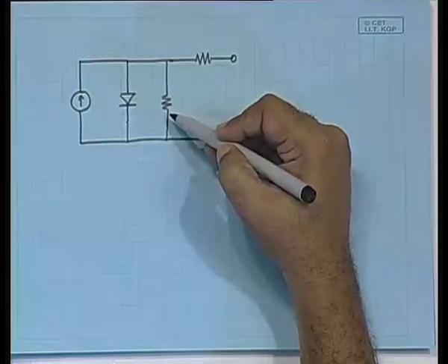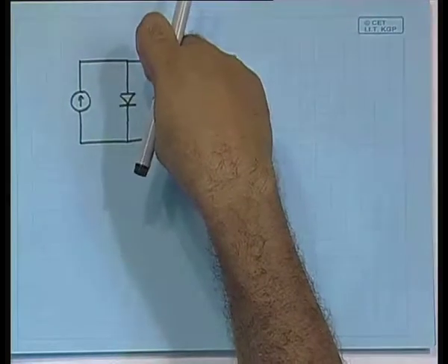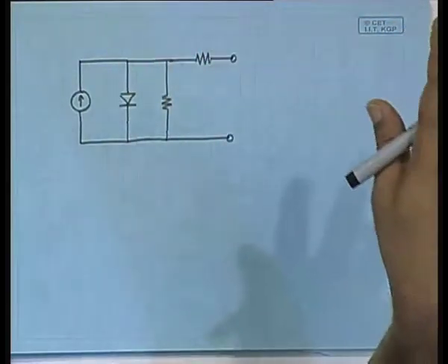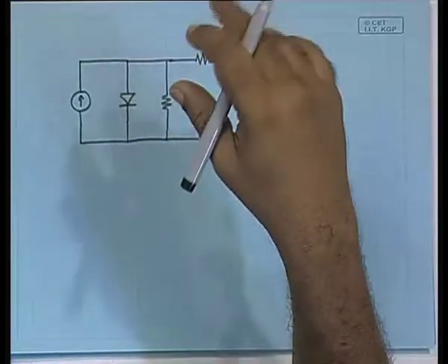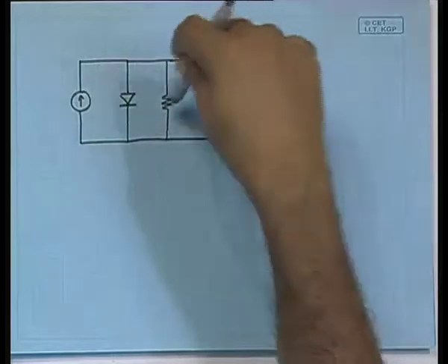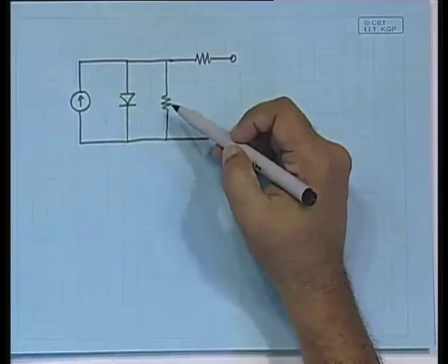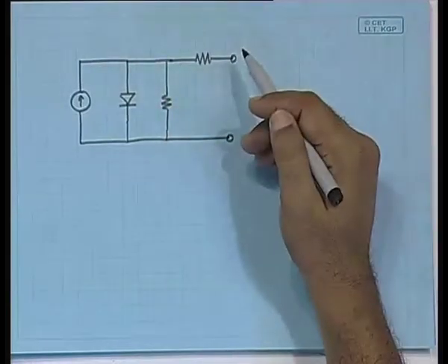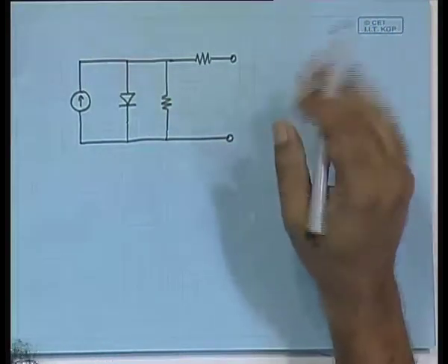on the recombination sites. If it is a perfect crystal, then the recombination sites are very small in number, mainly on the top. That means the top layer is of course exposed, they have dangling bonds. So, that is where mainly the recombination would take place, but if it is polycrystalline or if there is a deformity in the crystal structure, there are dangling bonds and they act as the recombination centers. For an ideal photovoltaic cell, this would be very high, close to infinity, but in actuality you will find if you measure in physical things, you will get something like a large value like 300 ohms or so, but nevertheless it is there.